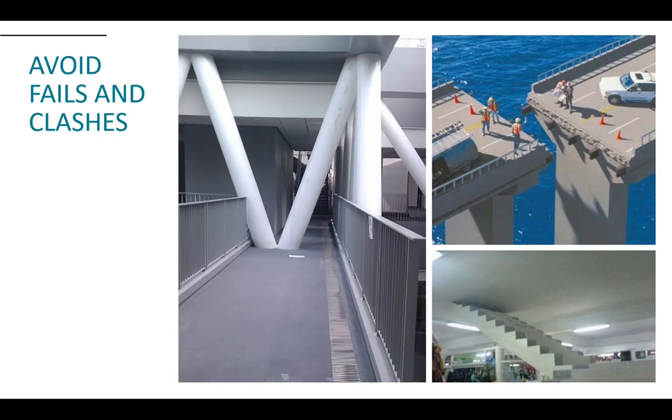That looks pretty real, and it's obviously got some significant issues. You can see that when it goes back to our BIM workflow chart a few slides ago, the cost of actually addressing some of these issues after they've been built would be significantly high. Obviously, these clashes might have been detected earlier on if we use the BIM process using Revit and then a software called Navisworks, which we'll use next semester.